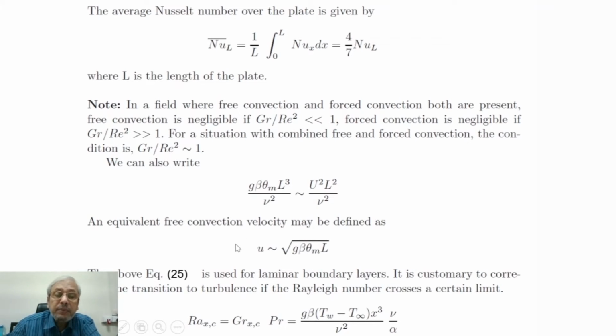So this gives the expression for free convective velocity, how a free convective or natural convection velocity can be created. If we know the volume coefficient of expansion, the temperature difference in the field, the distance between two points through which this temperature difference is acting, and g, then we will be able to calculate natural convective velocity.